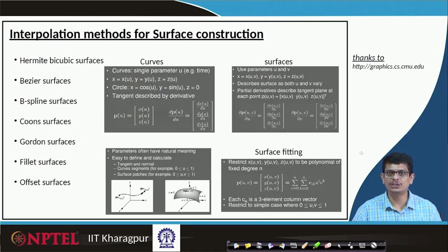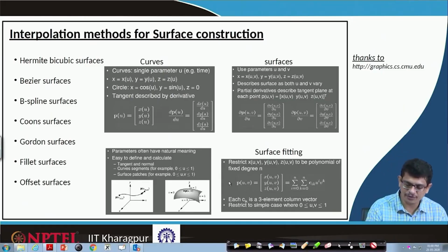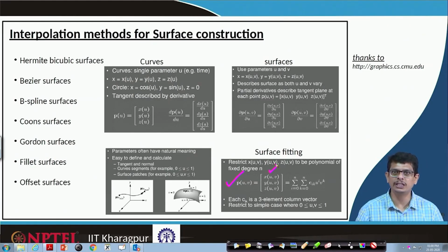Similarly, if we are going to construct surfaces, this polynomial expansion we will do not just in one dimension like x, but in the x y directions or u v parametric variations. So, looking at that carefully, the polynomial surface P as a function of u v, represented in terms of your x y z points throughout the space, whatever discrete points we have, can be expanded as a double summation, summation on i and summation on k.